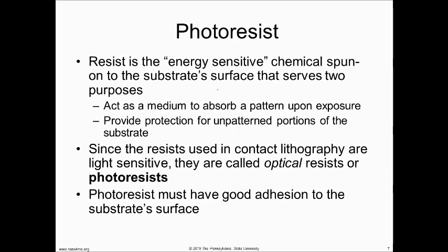So they're called photoresist because they're photoactive, which means they chemically respond to light. And they don't respond to all light. They actually have tuning agents in there, like chemical bonds, and these chemical bonds are going to respond to specific light. And the ones that we're going to look at the most in this presentation, which I'll talk about 3 times, is from probably the mercury vapor lamp. It has a spike in it where we have this energy-rich area due to the mercury vapor lamp constituents that's going to emit at 365 nanometers. And that's called the I line, and that's going to be our sweet spot. We use quite a bit for photoresist. So the photoresist itself is tuned for 365 nanometers.